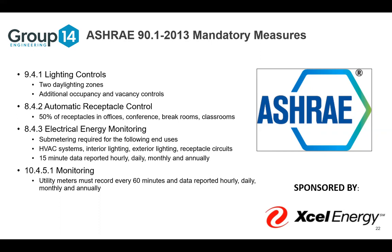So within ASHRAE 90.1 2013, you have additional daylighting required, additional occupancy and vacancy controls on your lighting, automatic receptacle controls required, electrical energy monitoring, so sub-metering of end uses, and then utility meter monitoring, say that 10 times fast, is also required.